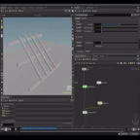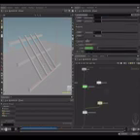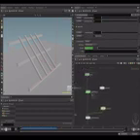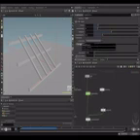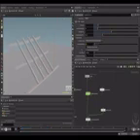This is because at each substep, the hard constraint is trying to hold on the pieces. As you can see here, this parameter is set to -1, meaning that it's driven by the bullet solver or rigid solver constraint iteration parameter. So if I change this, let's say to 2, you will see a big difference.